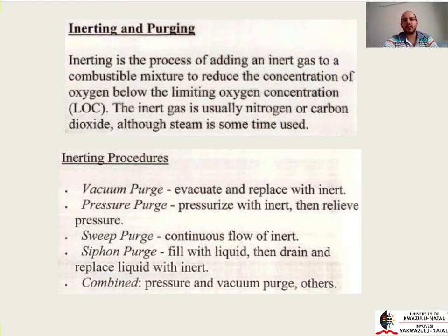Now we'd focus on storage tanks and other pressure vessels. So even vessels like reactors, for example. The storage and use of chemicals and of course the avoidance of combustion of those chemicals and compounds is typically achieved through inerting and purging.